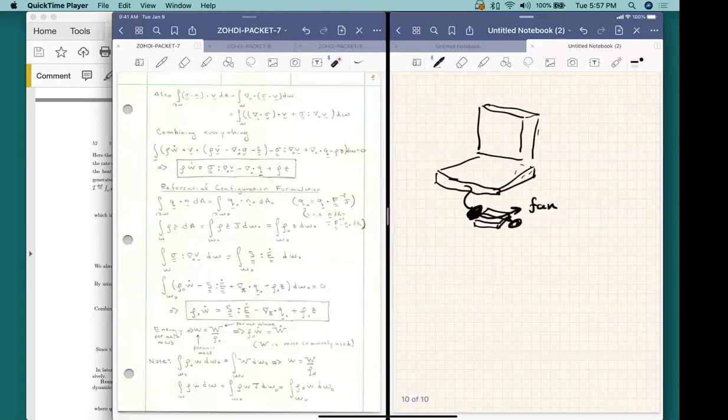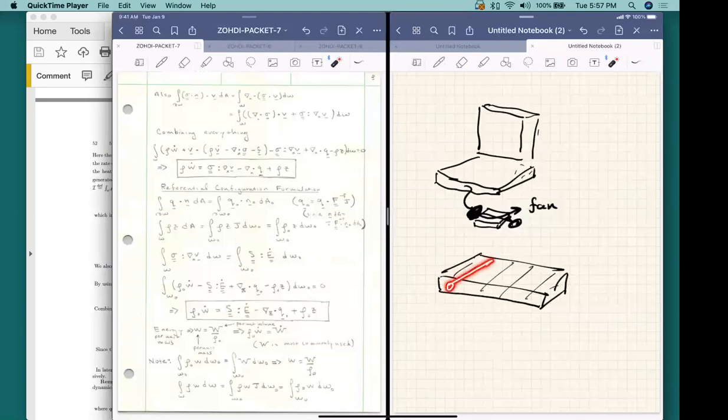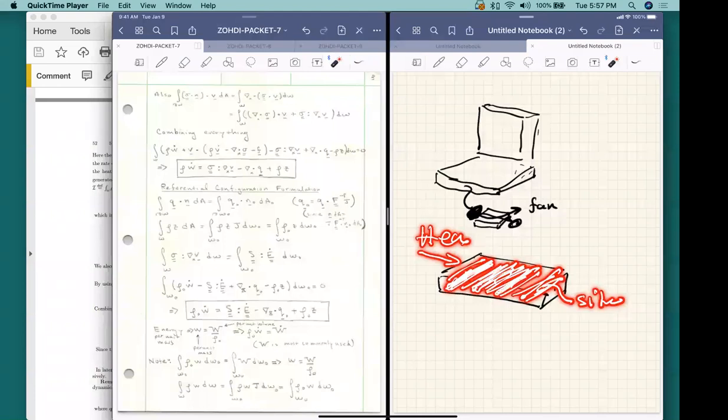As a very tangible example, if I take a piece of material, let's suppose it's PMMA or ABS, so it's just some kind of a plastic, and I come along now and I take some wires and I build micro wires inside this material at the small scale. So I'm drawing it exaggerated, but I put wires in a certain direction, and these are silver. Even though the heat might be coming from this direction, it's going to see the silver and do what? Well, it's definitely not going to flow against the silver. The heat is going to build up along the wire and